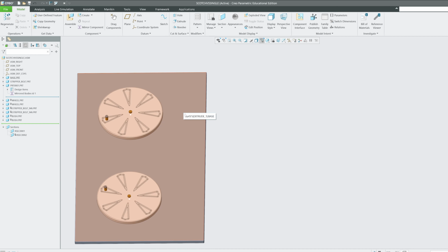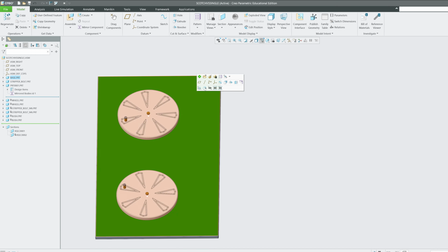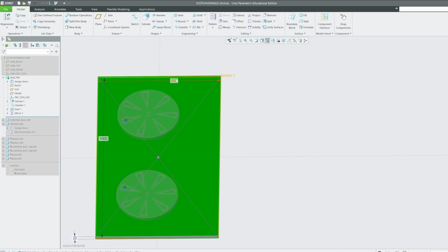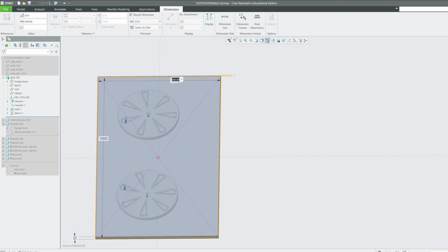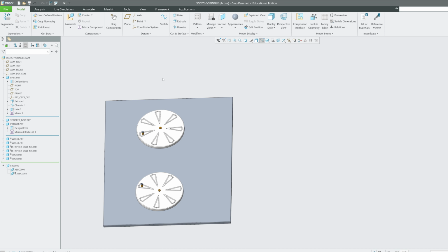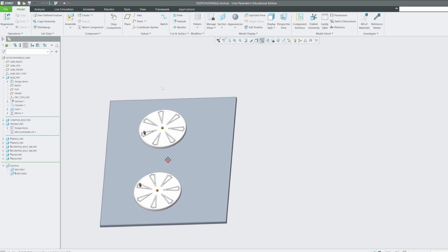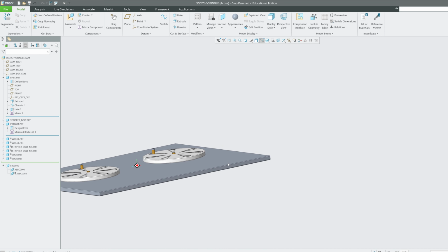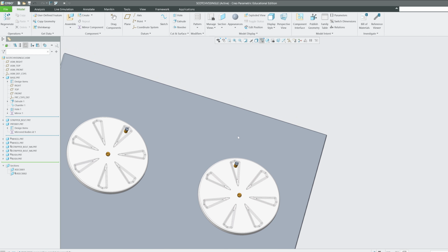Okay, now seems like we have made this much ready. Now time came to add a crankshaft, and seems like we also need to make this plate a little bit wider. Let's make it 800. Hope that this will give us enough room to play. Alright, so what I'm gonna do next is create a bearing, not thrust bearing, but vertical bearing that helps the rod to glide.